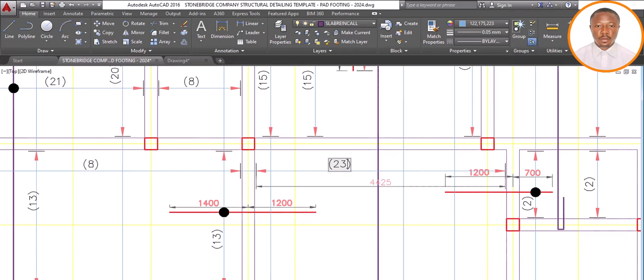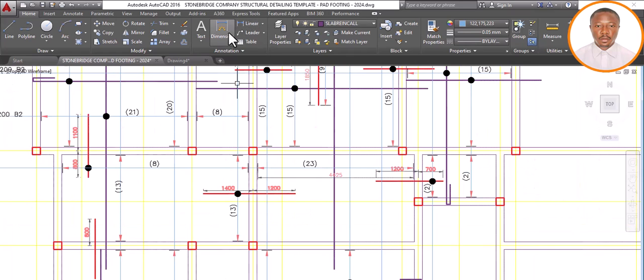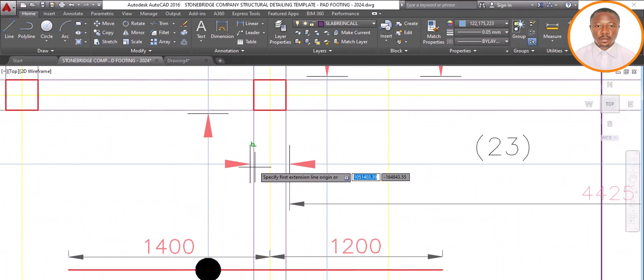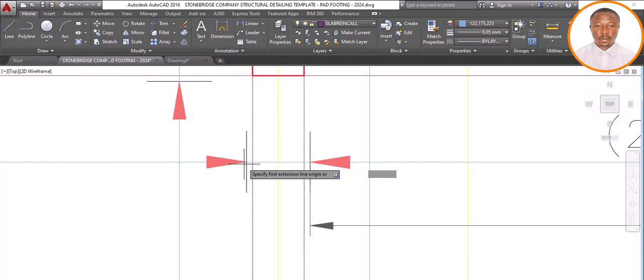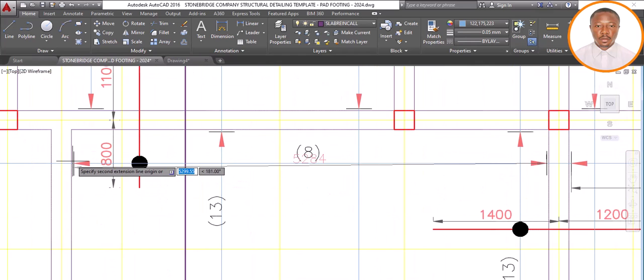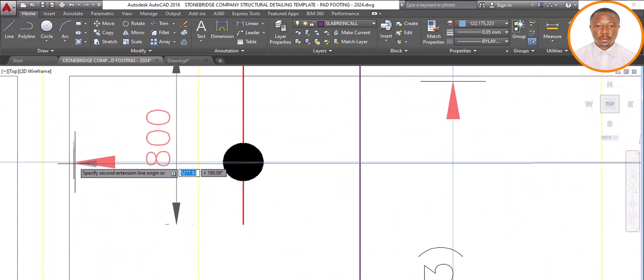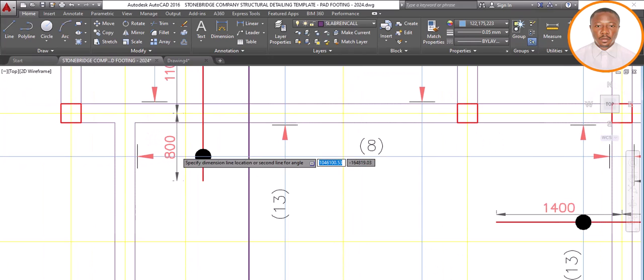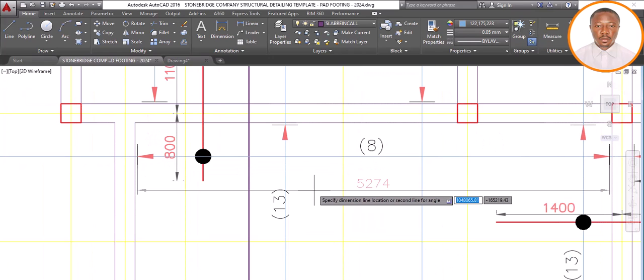That is that. So I also come here. We're done with this. So I also come here and take my dimension and see what we have for us to calculate. Let's do from this particular point, and we move to this point here. Now it's very important that you take your dimension and also divide. We are dividing by 200. That's our base spacing, because from our Prokon structure, that's what we got.